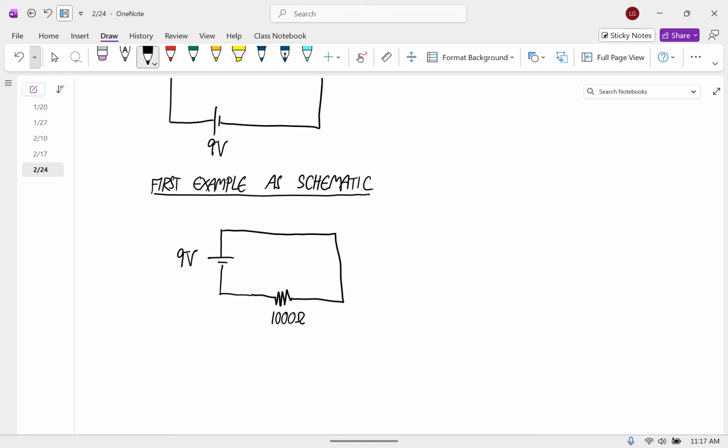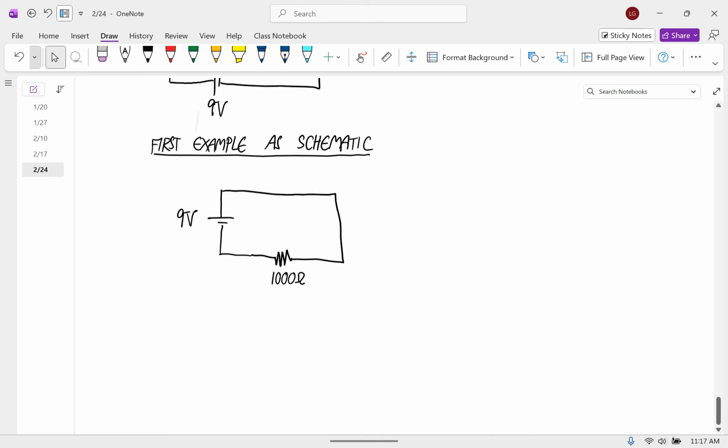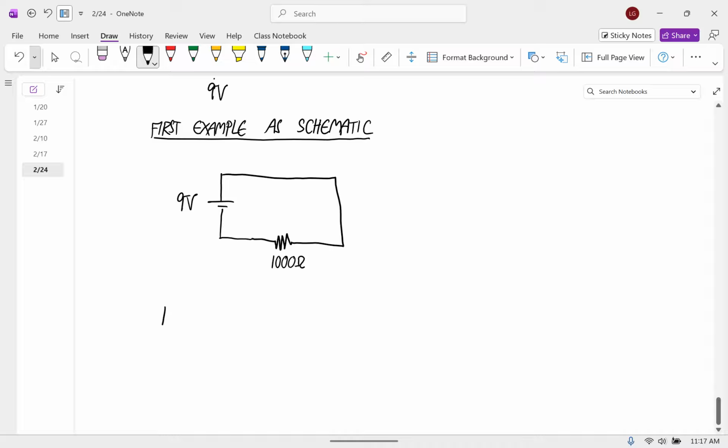There is something else. We're going to use resistors, like you asked about before, to control the amount of current that a device gets. So if we have a power source that would be producing too much current for a device, we'll use a resistor to cut that down into the range that we want. There are some other tools with resistors that are going to be important for that, and so I want to talk about resistors in series and parallel.